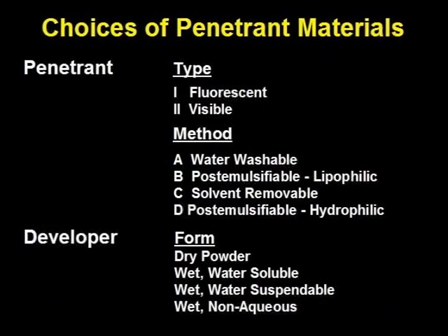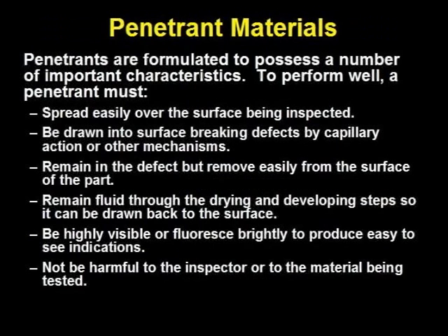The first task when conducting an inspection using PT is to choose the right materials for the job. Each combination of materials has its own advantages and disadvantages, which will be discussed in the following slides. Penetrant materials must possess the following important characteristics: spread easily over the surface being inspected, be drawn into surface breaking